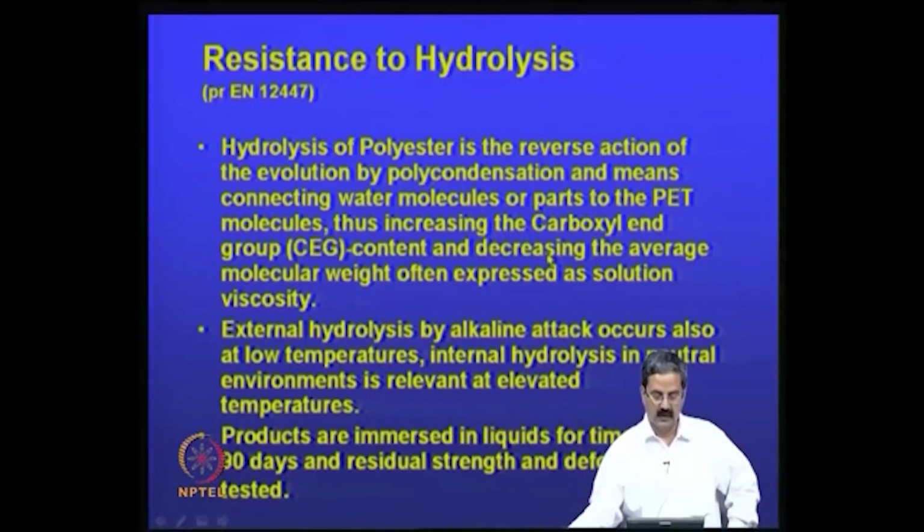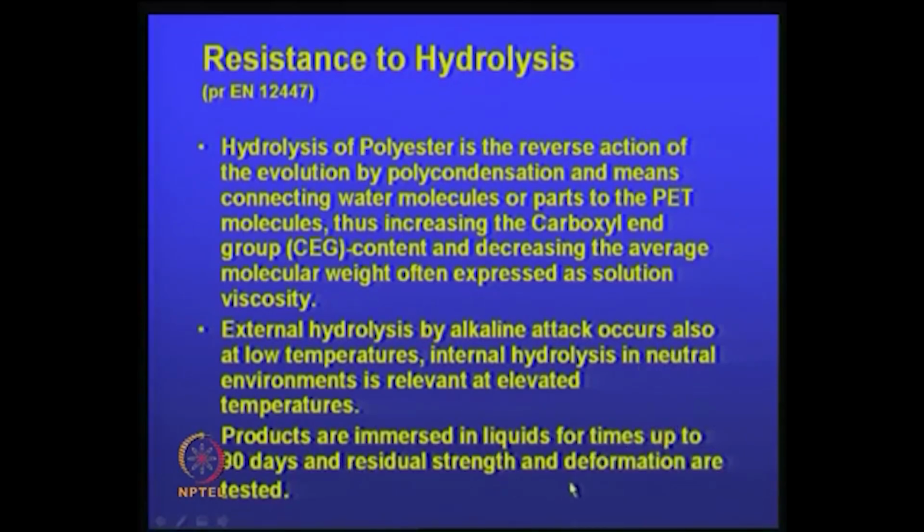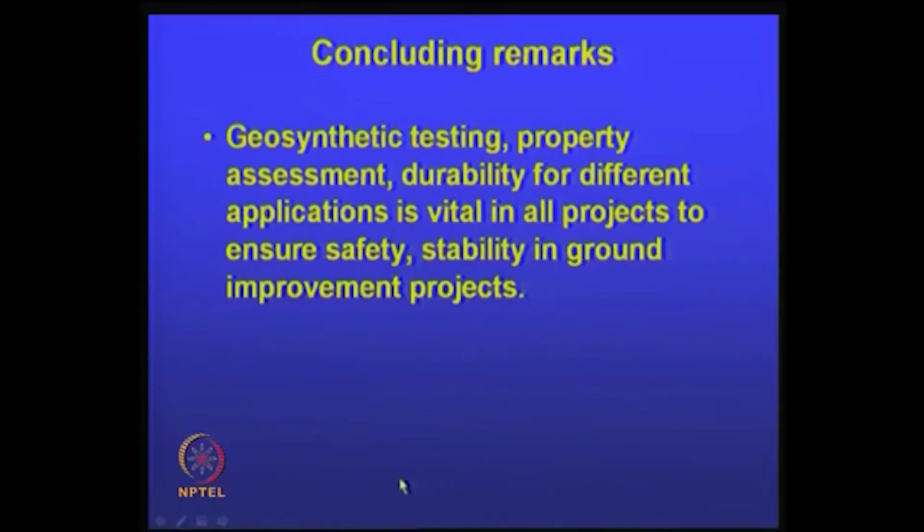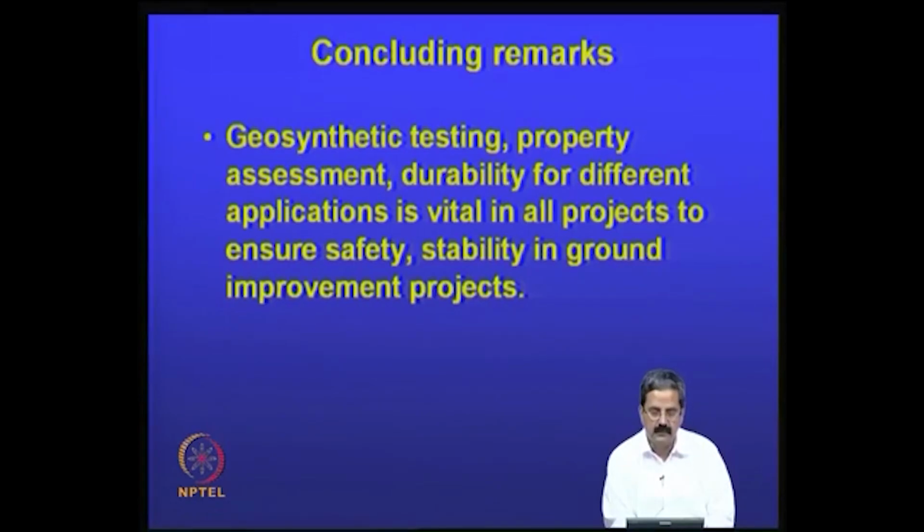Why those things happen is that, due to this hydrolysis, the average molecular weight will come down actually. So there are a couple of tests that are done. What we do is that the products are immersed in liquids for times up to 90 days and residual strength and deformation are tested. So you have a number of tests in this manner, and a number of testing procedures which are well established.